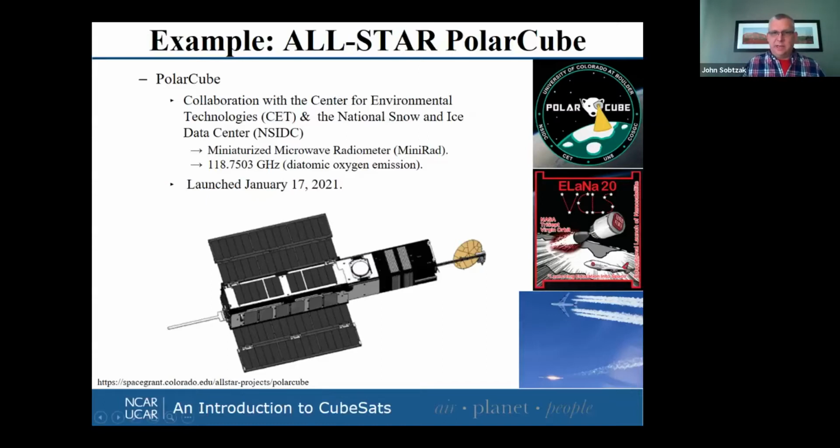But in the satellite, you see the radiometers up top here, and the reflector dishes to help collect data. For those of you in EOL's remote sensing facility that knew Bernard Wang, he helped design this reflector when he worked for Dr. Albin Gasiewski over at the university. I believe this is a reaction wheel assembly in the middle. There's a UHF antenna off the back, oriented in such a way as to minimize any interference with the radiometer, even though they're at extreme opposite frequencies. And the rest of the bus is included.